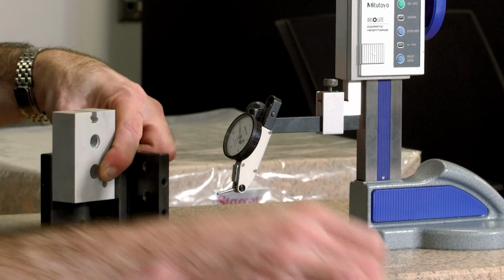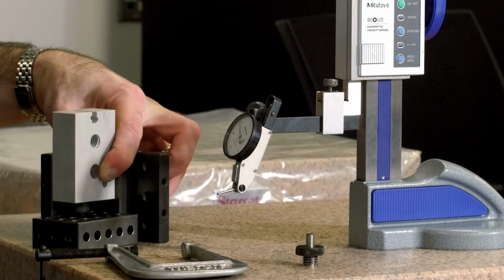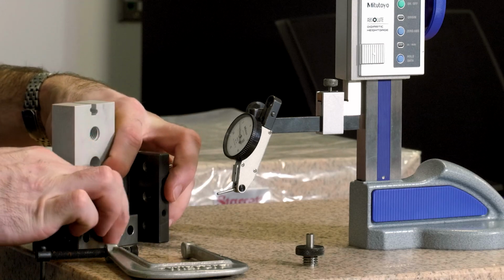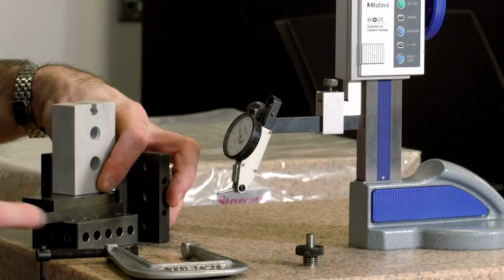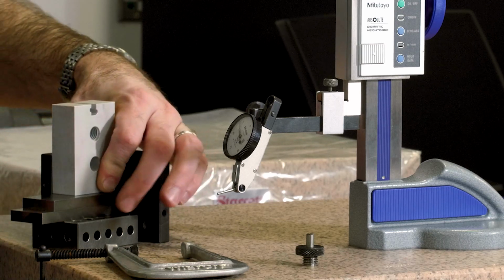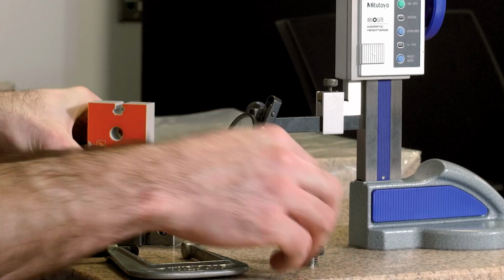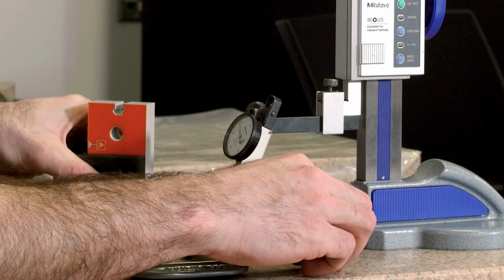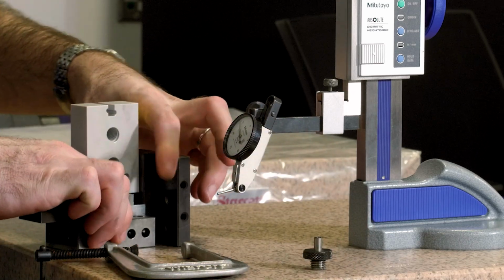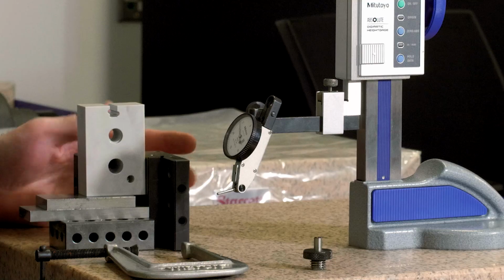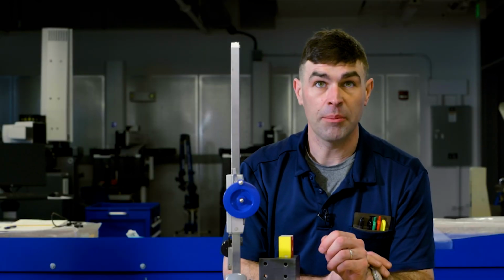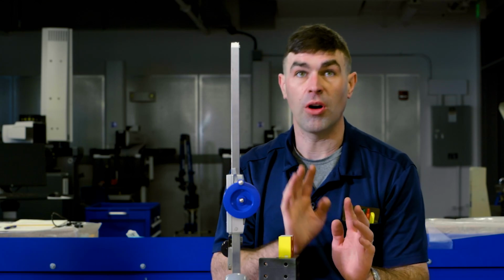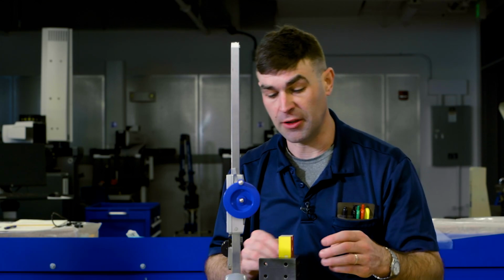So, and this is not perfect by any means, but it'll work. I'll create a stack of precision, flat things. So a 1-2-3 block and some gauge blocks. And that will get me above here, and it's going to clear this. Okay. Now, you might say, well, isn't there tolerance stack up here? And you'd be correct, there is, but keep in mind, these all have very, very small tolerances in the tenths of thousandths. So for our demonstration here, it's not going to be a big deal.